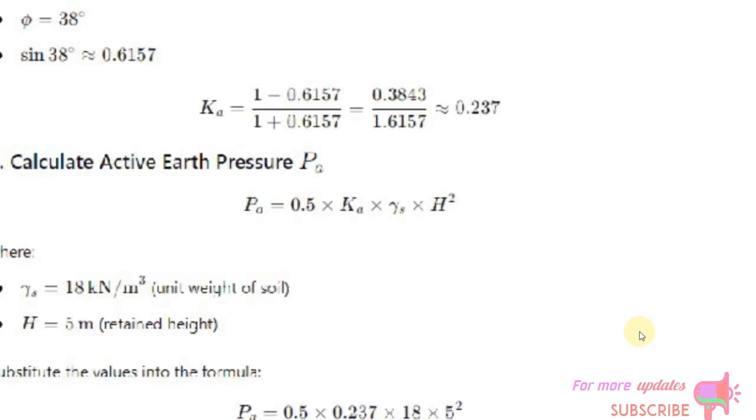The angle of shear resistance is equal to 38 degrees. The factor of active pressure equals 1 minus sin of the angle of shear resistance divided by 1 plus sin of the angle of shear resistance. Active pressure equals 0.5 multiplied by the factor of active pressure multiplied by soil unit weight, 18 kN per cubic meter, multiplied by the square of the retained height, which is equal to 5 meters. Surcharge pressure equals the active pressure factor multiplied by surcharge load multiplied by retained height.